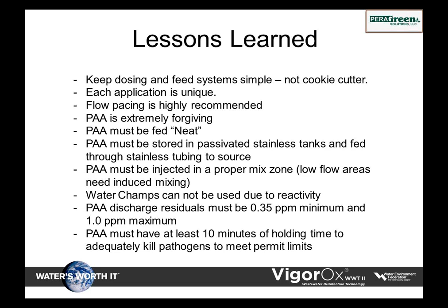Then what you do is maintain the residual and give it the holding time to get the rest of the kill. Right now, we're recommending passivated stainless tanks and feed through stainless tubing. You take a look, that may be expensive up front. You're using smaller tanks, you're using tubing, smaller pumps. If you're putting a new installation in compared to chlorine, it will be cost equal or less based on the footprint. You may not need the footprint for cement. So again, you keep it simple.